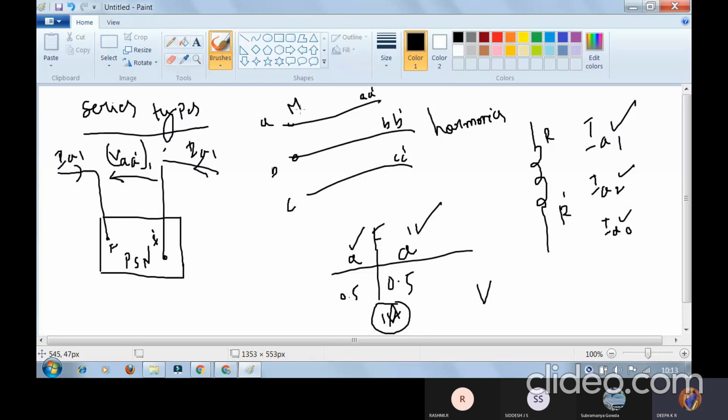You're going to have a transmission line. As I said, take an example: this is a transmission line. You determine where the fault exists in the series system, and that is why it is named a series type of fault. Based on the open conductor as well as the series connection with the transmission line, we segregate it into one, two, and three conductor open systems. Again here we move with three different calculations: one conductor, two conductor, then three conductor. So take down the heading: one conductor open fault.